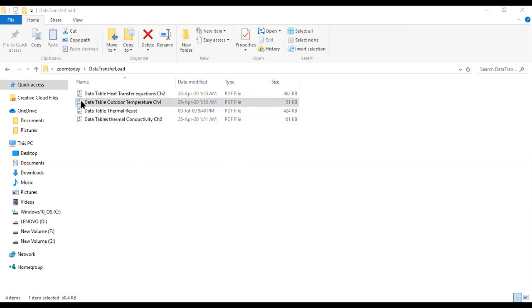And I will just zoom it for you. So this is design temperature data, but unfortunately this is for American cities, big cities. Like this, you will find Pakistani data also, and it is available on the internet. It is available in the ASHRAE handbook. It is available in other international handbooks. So you can find out Karachi, Islamabad, Lahore, these temperatures.